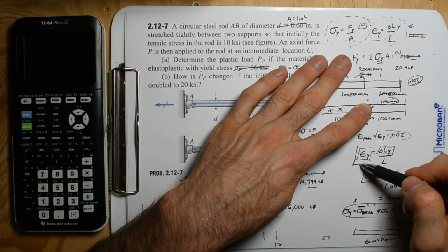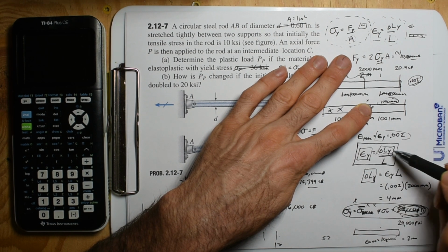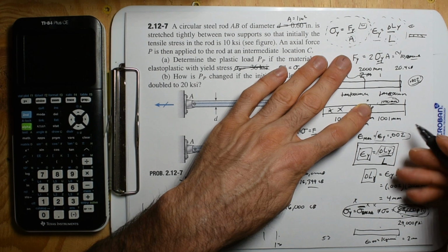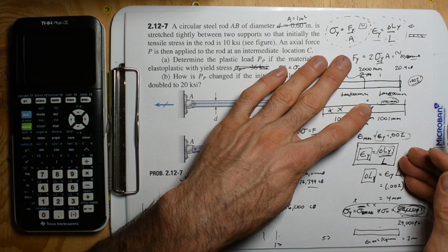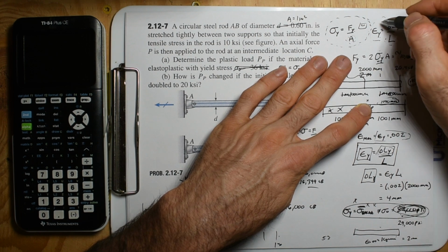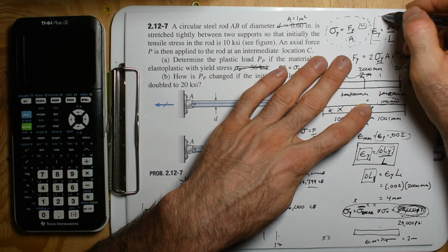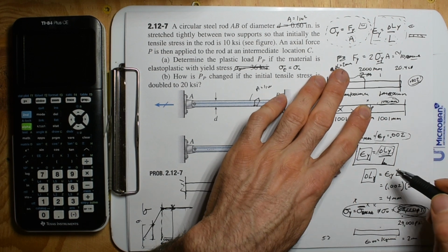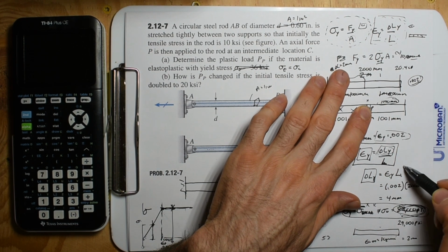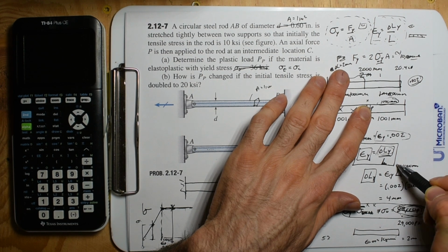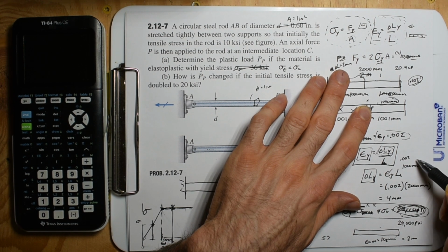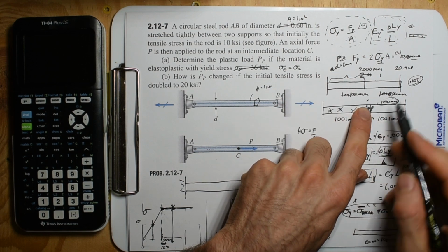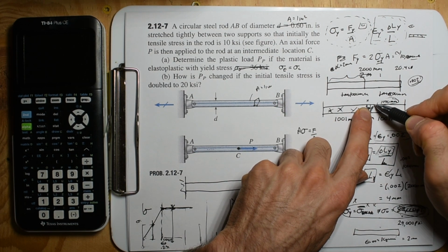But I just didn't do this as an undergrad. I didn't realize this was an actual equation that you just get to use. For whatever reason, the textbooks hide it from you. I swear to God. But anyway, let's do it. We rearrange the equation. We have the initial length of 100 millimeters. Our max strain is 0.002, and we get 2 millimeters. So now that this one is happy as a clam, we can make it go 2 more millimeters.